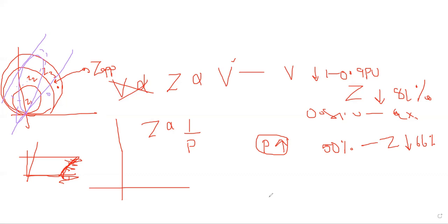That is also one of the indications to bypass these load encroachments. Yes, this is a power swing or load encroachment. Using quadratic characteristics, lenticular characteristics or blinders, we can achieve this. And to block the load encroachment, since faults are mostly unbalanced, we can check whether the negative to positive sequence ratio is greater than the threshold, or use negative sequence overcurrent elements. During a fault there would obviously be a drop in the voltage.